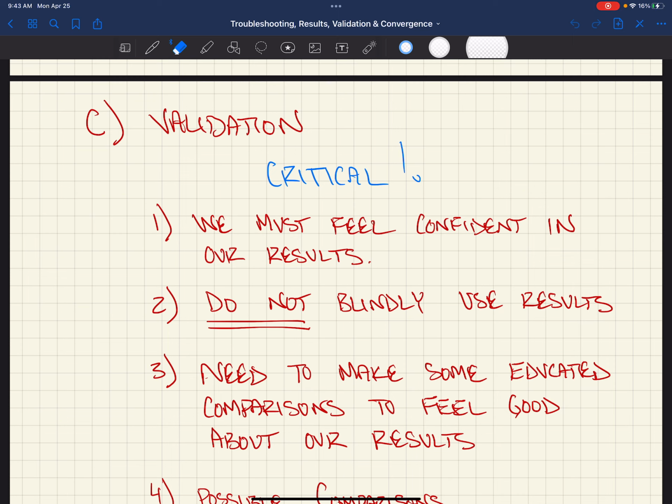It's still critical, right? Still allowing you to make sure, because it could run, obviously, when you get it running, the amount of dead load you put on it, you could vary that fairly significantly and still get results and just be unaware of the fact that you made the mistake of moving one decimal point in one of your applied dead loads or live loads. The model runs, everything's doing great, but overall, that amount of load you missed, right? You missed the target just because you moved a decimal, right?